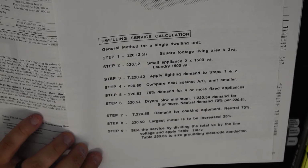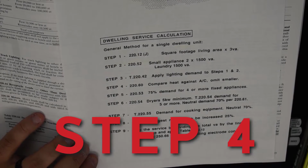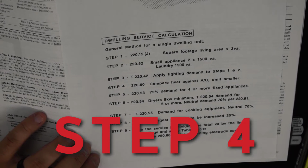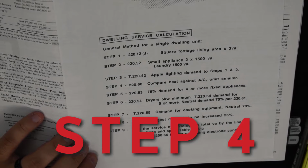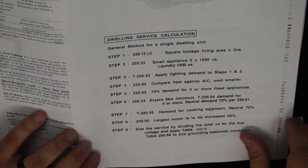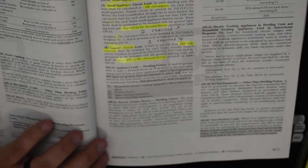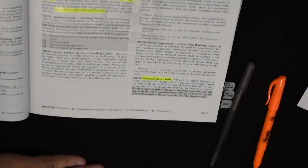Now we're going back to our step-by-step format and we're going to look at step number 4. And step number 4 takes us to a piece in the code that doesn't have a whole lot to speak on, but we're going to look at it. It says 220.60, and it says compare heat against AC and omit the smaller. So let's turn to 220.60 and we'll highlight non-coincident loads.